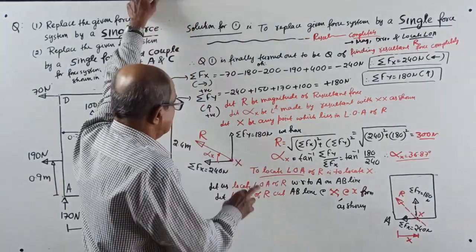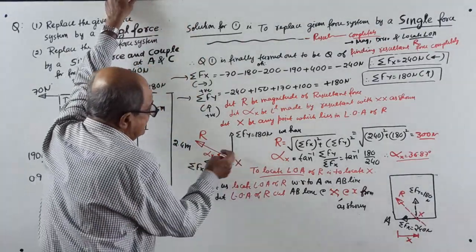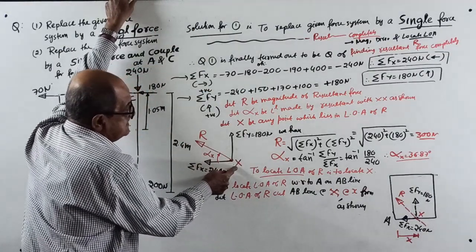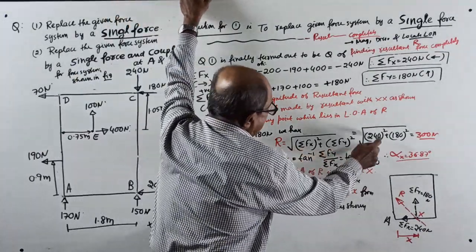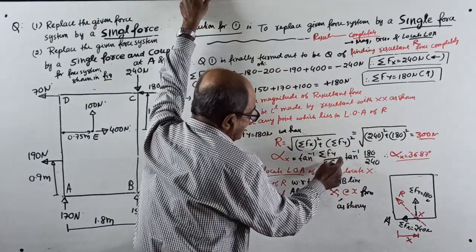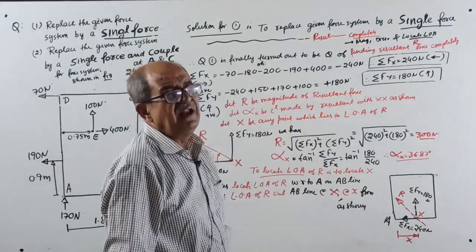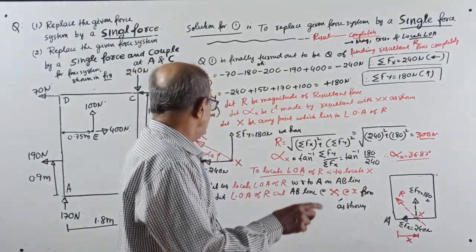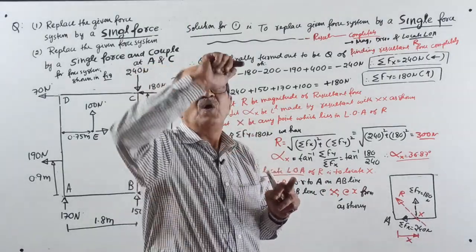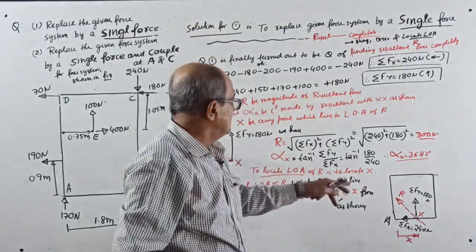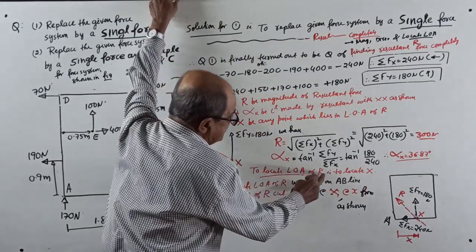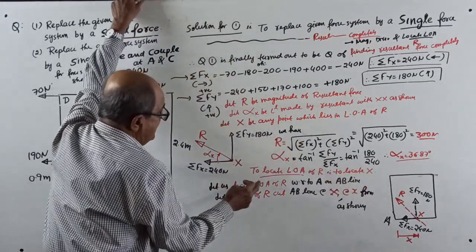Okay, over. Start. Sigma Fx left side, sigma Fy up, resultant R, angle alpha x, and x is any point. These you all know. Square root of sigma Fx squared plus sigma Fy squared gives 300 newton, and tan inverse of sigma Fy by Fx. This earlier I used to tell 3-4 times. Angle measured with x means tan is opposite y by x. Now I will not tell. 36.87 degrees.